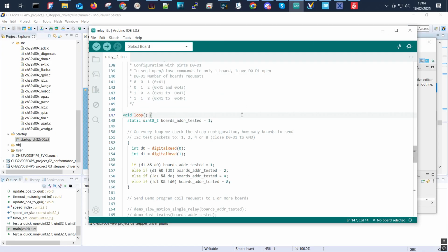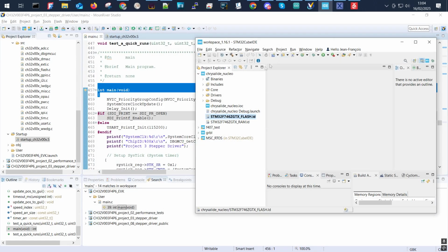In Arduino we can use C and C++. Other IDEs usually provide mostly C, and we can also use C++. But there is often an impact on the footprint for lower-end microcontrollers. So it is not that easy to use C++ typically for small embedded microcontrollers. The default is usually C.